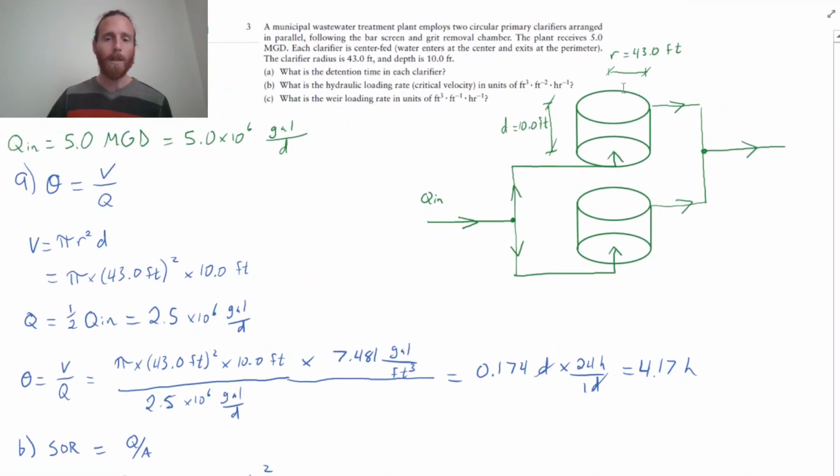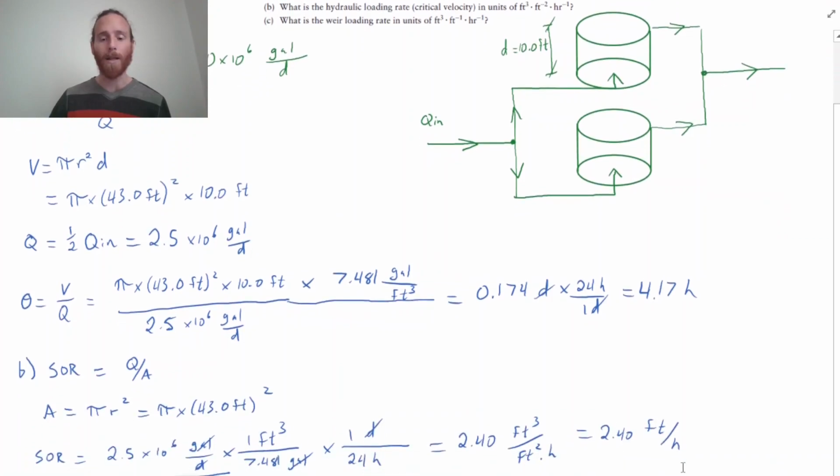Now, the reason this is important, so remember that the cleaner water, the settled primary wastewater, is flowing over the edge all around the perimeter uniformly. And we've got that weir running along the edge. Now the weir just looks like a sawtooth shape along the edge. But the reason the weir overflow rate is important is because if we're flowing water over the weir at too high a rate or too quickly, that will create turbulence. Now, imagine trying to settle sediment out of wastewater when there's turbulence. It's just not going to work. So, in any design, you have appropriate bounds for your weir overflow rate.